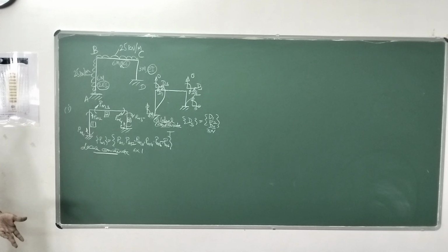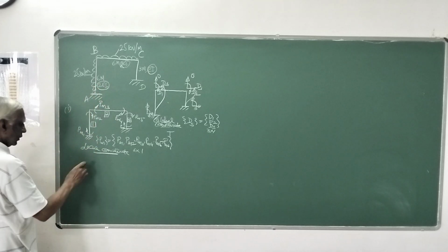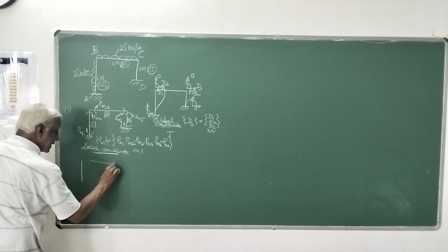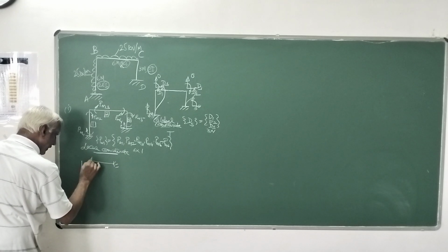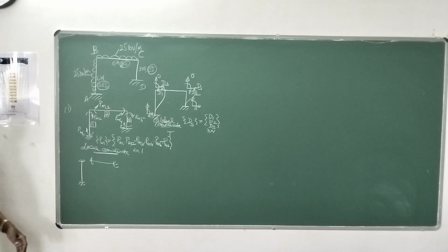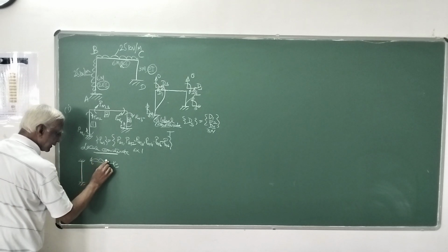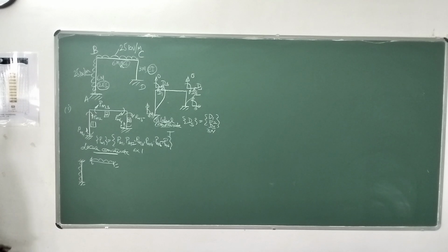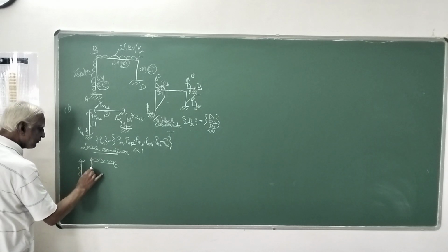How to find the equivalent joint forces? Don't allow any displacement, assume each end of the members to be fixed. Like this, whatever node is there on the member, due to that load, whatever reactions are going to develop, you determine.